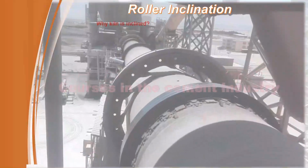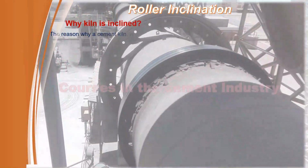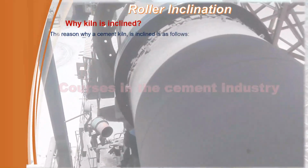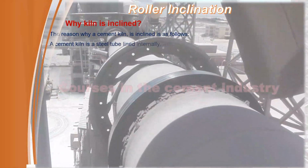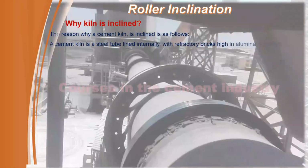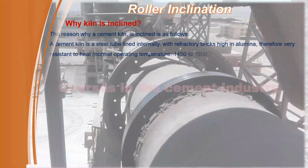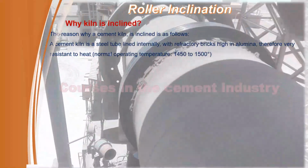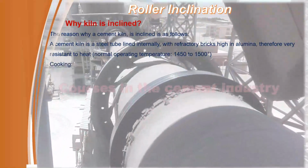Another definition of roller inclination. The reason why a cement kiln is inclined is as follows. A cement kiln is a steel tube lined internally with refractory bricks high in alumina, therefore very resistant to heat. Normal operating temperature is 1450 to 1500 degrees.